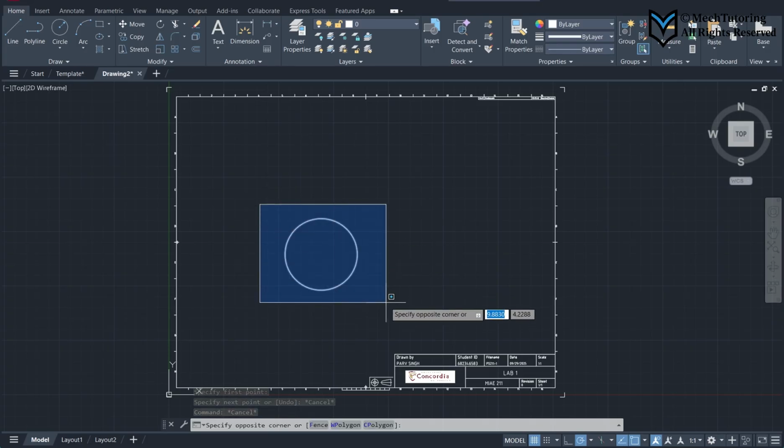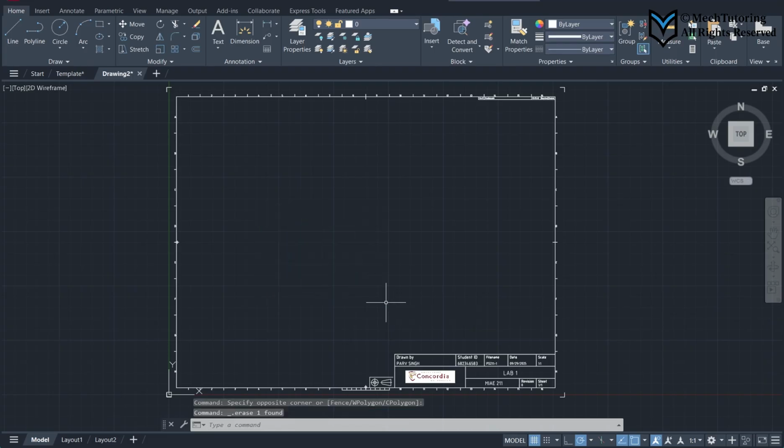I'm not going to tell you from next time what I'm using them for. I'm just going to use them because you know how to deal with them. If you want to disable them, you can just click on this and click on this. There will be no snapping on the drawing. Sometimes there is way too much snapping while dimensioning, so it's better to turn them off, because it will be easier for you to do the dimensioning. So I'm going to turn them back on again.